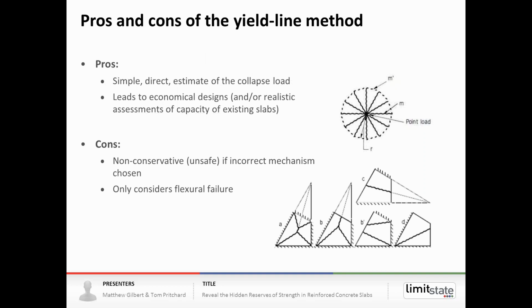Another con is that it only considers flexural failure, so you will need to do additional checks for things like punch and shear failure. And obviously, as an ultimate analysis tool, it also doesn't give you any indication about deflections under service loads.